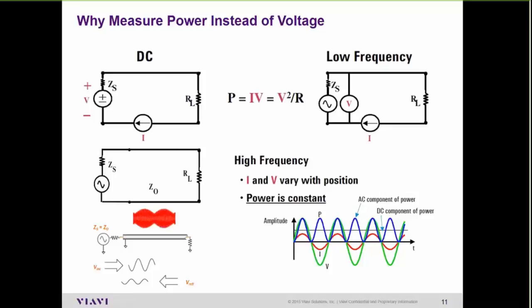But with RF, you have a lot of different frequencies over, say, a 10 or a 20 meg span. And when you start getting those frequencies that mix and sum, now all of a sudden it's a lot more difficult to measure power with just varying voltage. So with those types of systems over 1 gigahertz in frequency, you really have to have an average power meter versus trying to use something like just a voltage setting where you crank up the voltage a little bit.